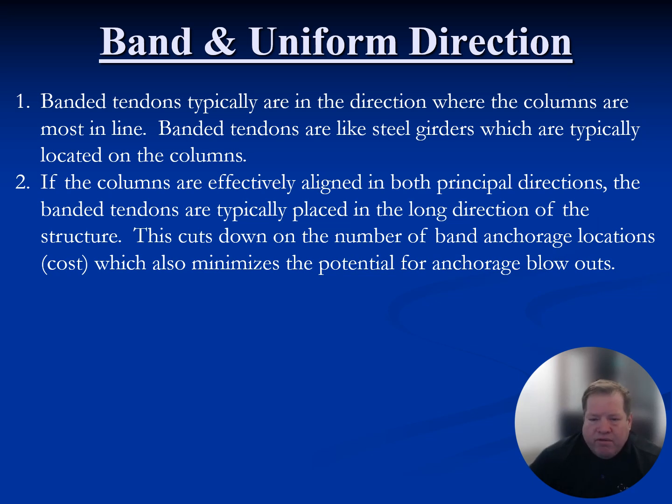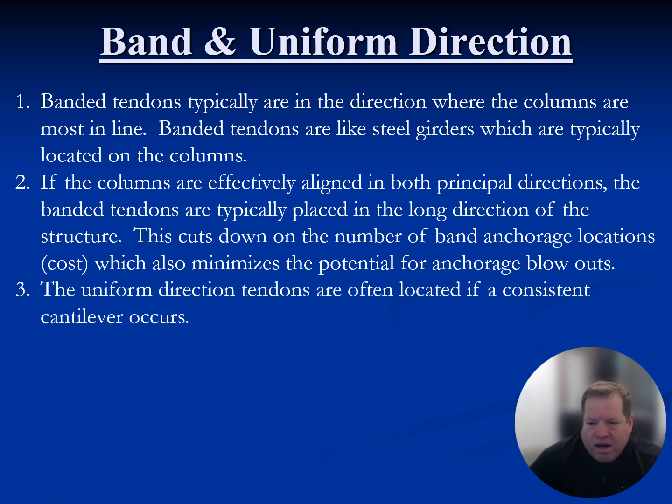If you have 8 column lines in the long direction, but 40 in the short direction, having the bands go in the long direction decreases the band anchorage reinforcement, which is a cost savings. But if that doesn't work for you, it doesn't have to; that's purely an economy standpoint. You could easily do it in both directions.